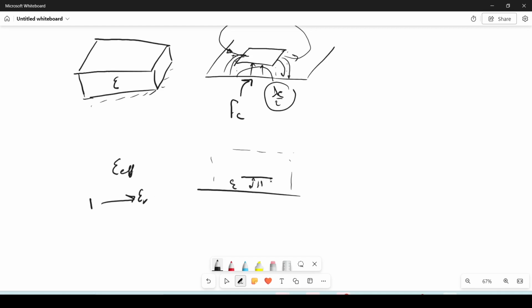So how do I decide? Generally we know that, for example, in the extreme case when the substrate is so big, like I have something like this, infinite, so here it is infinite length, and here too, but here is free space and here is epsilon r, the value of epsilon effective is basically the average, right? In this case epsilon effective equals epsilon r plus 1 over 2.